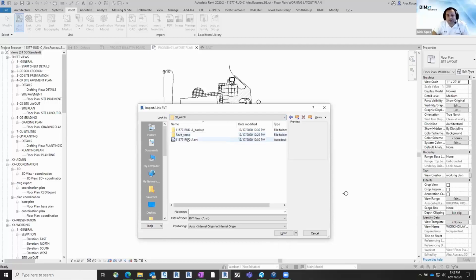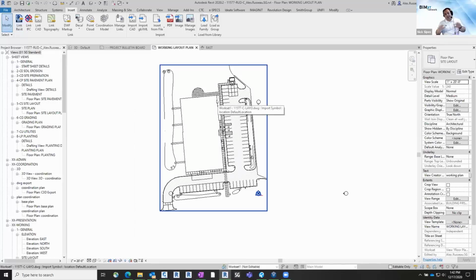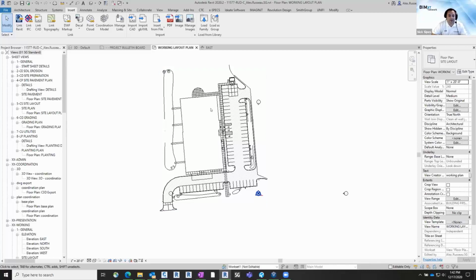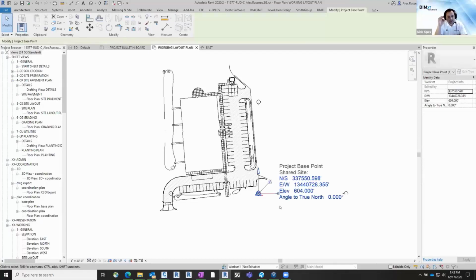Well, I was going to ask you to go back because there's 2 things about what you're showing that I'd like to point out to people. One of them is a change that wasn't really well noted in Revit. I think it was 2020. But if you select your project base point, a lot of people are like, oh, if I enter the values here, I can move it into the right place. When they got rid of pinning and unpinning the project base point, if you enter values into the parameters, it will actually move the project base point away from the internal origin. And that's a little catch that a lot of people don't know about.